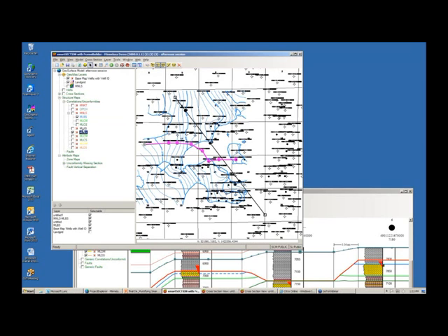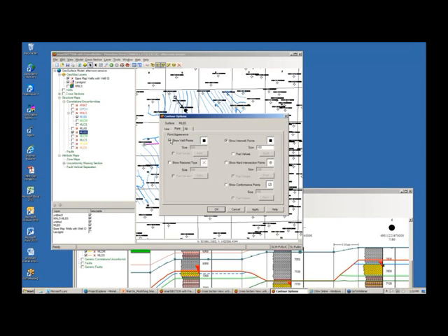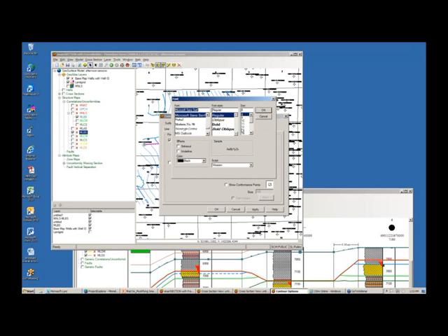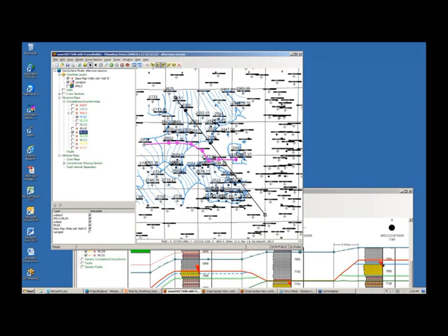One thing that's really useful is you can come in here, change the contour spacing, and most importantly, you can actually show the values of your points. This is one of my favorite features. I'm just going to boost up the size here so we can get in here and see it. You can see your data points right on your map, and they will correspond to your surfaces being picked. So I think that's pretty much it.